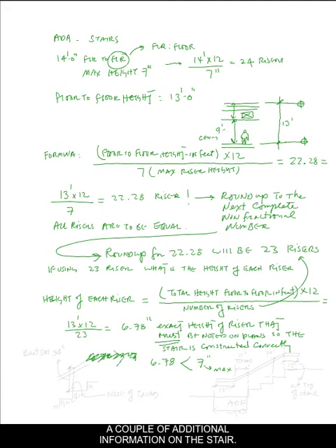A couple of additional pieces of information on the stair. The handrail on the stair, if this is your riser, the handrail as it goes up is measured from the nose of the tread.